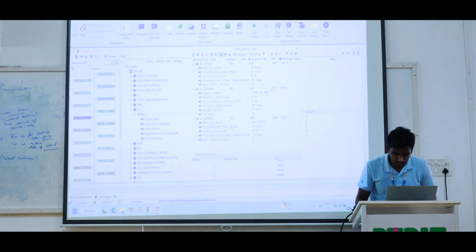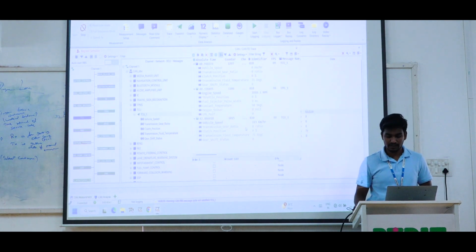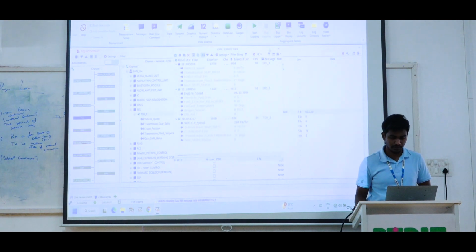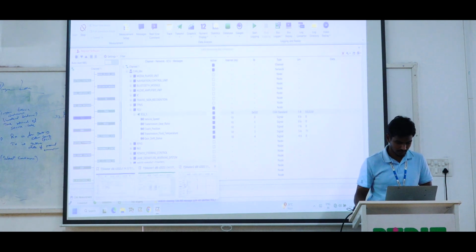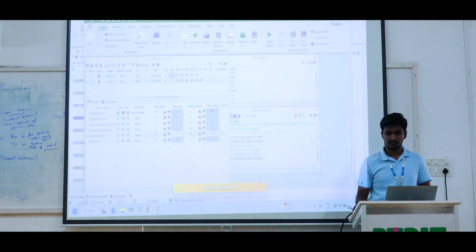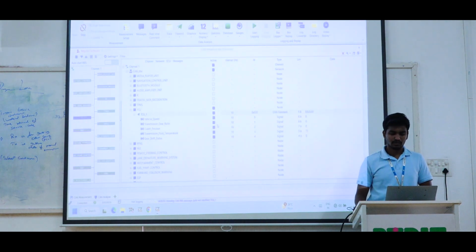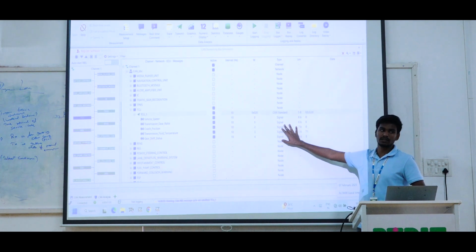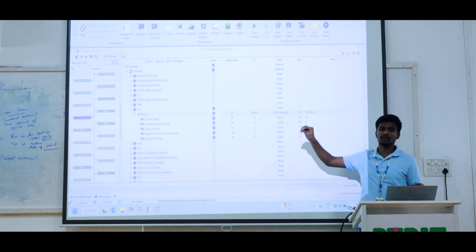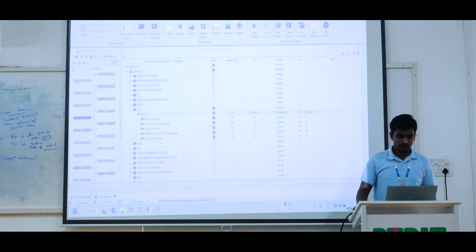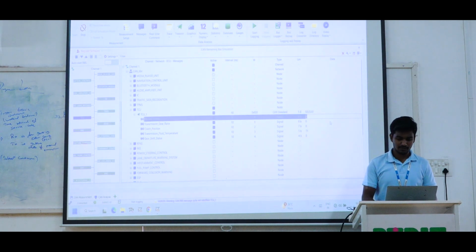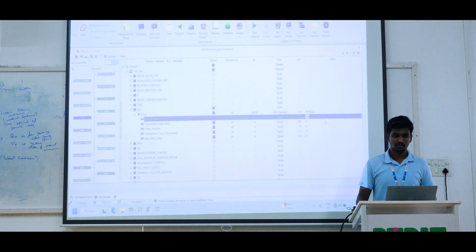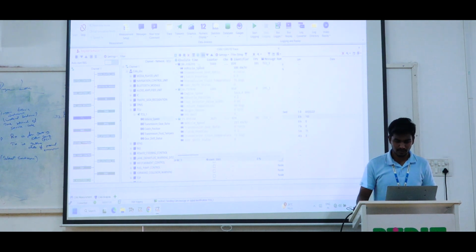It is showing vehicle speed as 0, which means the previous windows are still open. Please close them. We don't need different kinds of tabs. We are going to work with only one tab, where we simulate the value, or else we have to work with CAPL scripting. Once you activate the DBC, then the node message, then give the vehicle speed. For example, 100 km/h, then check the trace window. Now it is showing only one message, vehicle speed is 100.